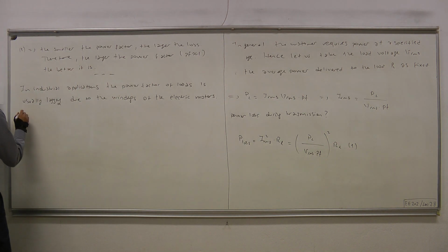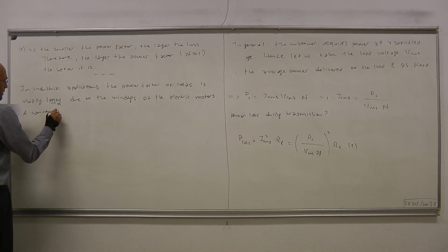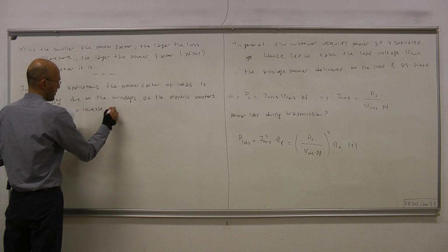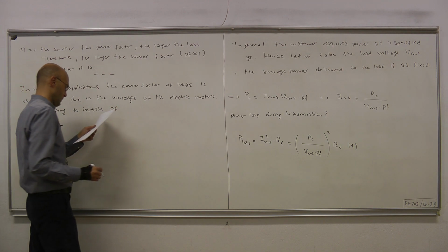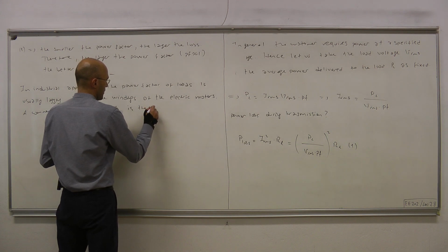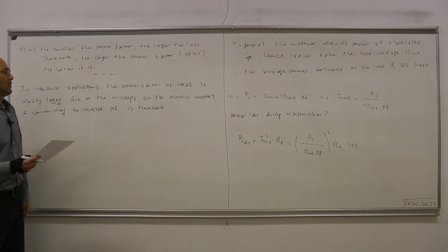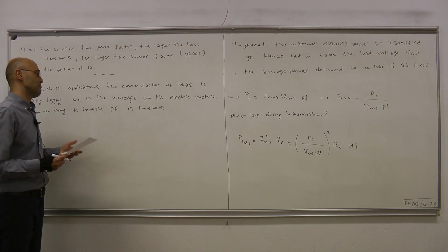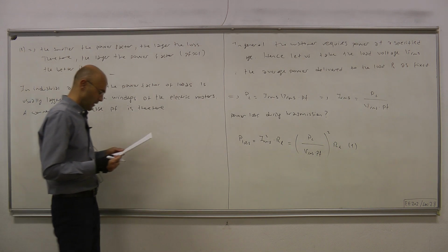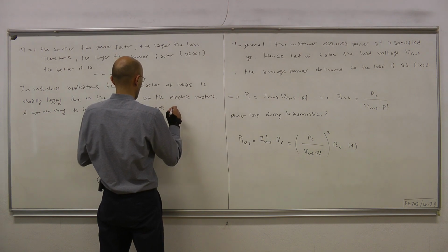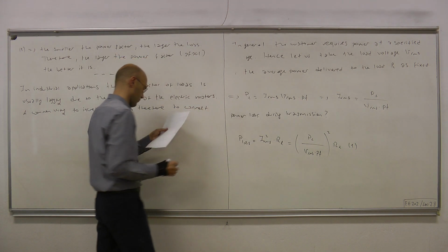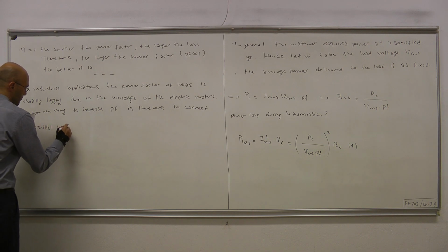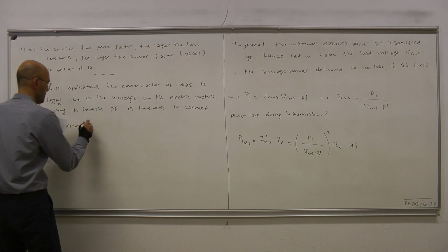Okay, and a common way to increase the power factor is therefore to introduce some capacitive effect, and that can be done clearly by a capacitor. It's therefore to connect a parallel capacitor to the load.